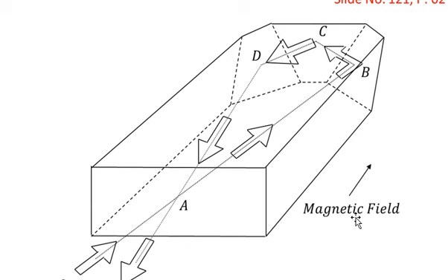Because the magnetic field provides a Faraday rotation, the polarization is rotated in such a way. If the magnetic field is not present, the polarization will not be rotated, will not be under control, and of course any other state of polarization of the beam coming from D to A will also be reflected back and will be supported for back reflection into the laser cavity.